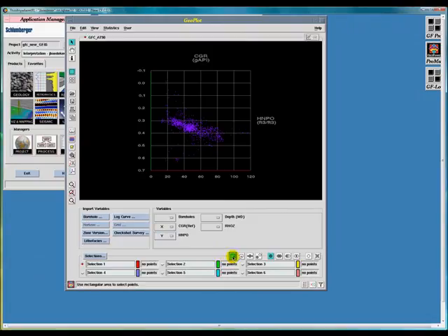We've seen a selection of points in crossplot using the rubber band rectangle option. This is one of the selection types in the Selection Areas feature in the Geoplot application. Other selection types include Polygon Area, Edit Polygon, and Select Area to clear. Let's now take a look at selection using a polygon area. Toggle a different selection box, then highlight the polygon icon. Then use the left mouse button to select the polygon vertices, then the middle mouse button to close the polygon.